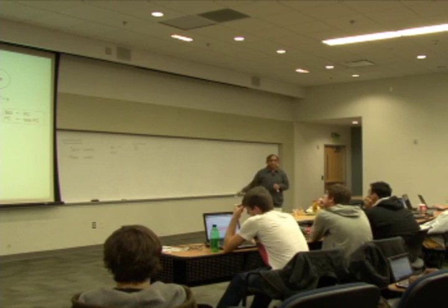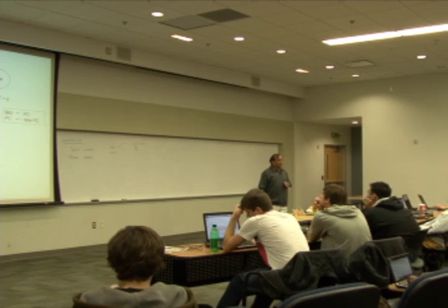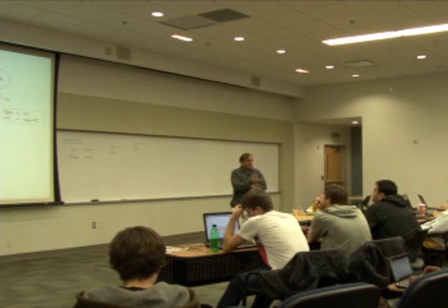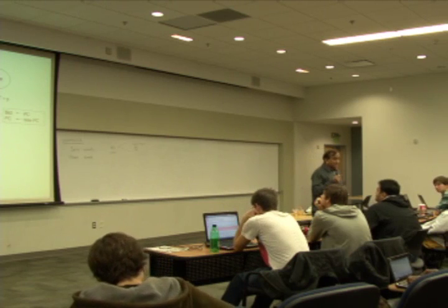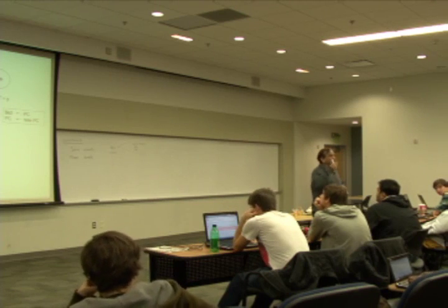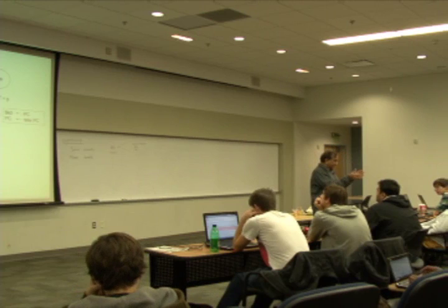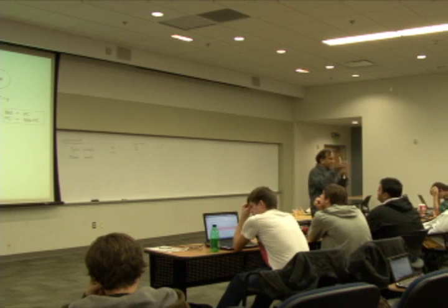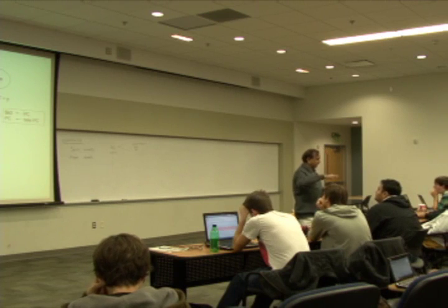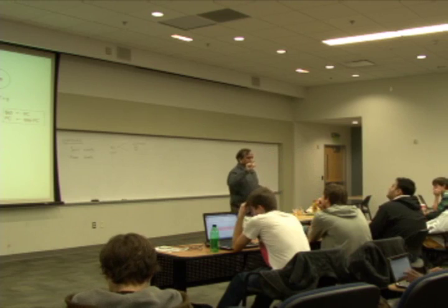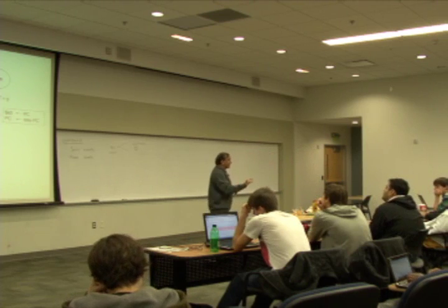Where does it get this new PC from? Where does it get the new PC from, Ron? It's a table, right? So the register gives you the index into the table. You go into the table, and that tells you exactly the address you want. So the IVT, the interrupt vector table, contains the address that corresponds to this particular discontinuity.